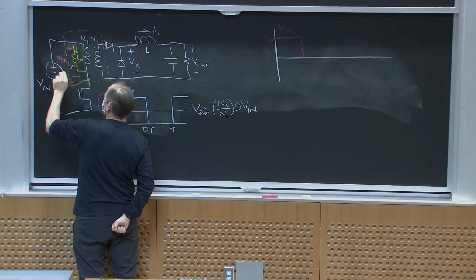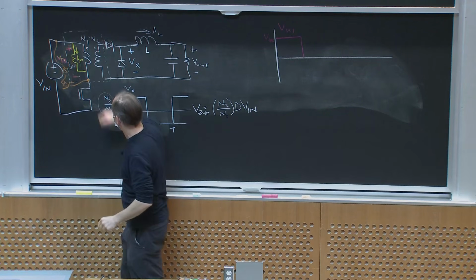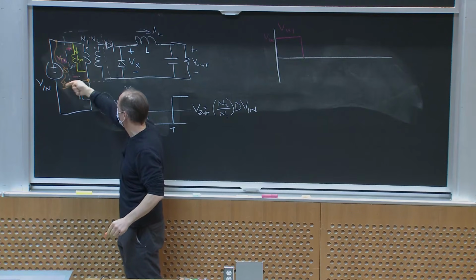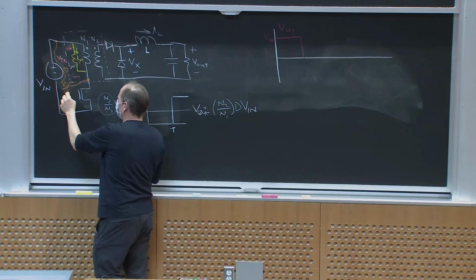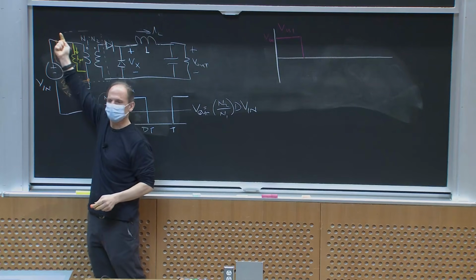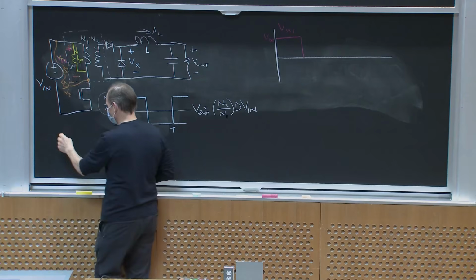And then I will put a reverse diode here. And so what this does is this lets this magnetizing current flow into this orange path against some voltage, Zener voltage VZ, and back up here. Okay, so this orange path is another path for current to flow through.